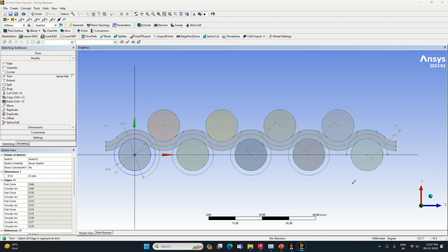What we are trying to do is prepare a path so that we can prepare a fluid zone inside. That will be the easiest way of doing it, because selecting the internal cavity is somewhat difficult. So let's have this. Ensure you are doing it properly, otherwise there are chances that there may be errors when you prepare the geometry.